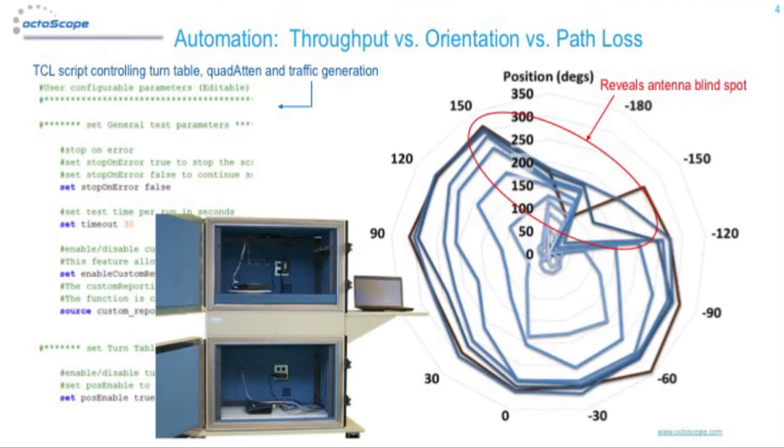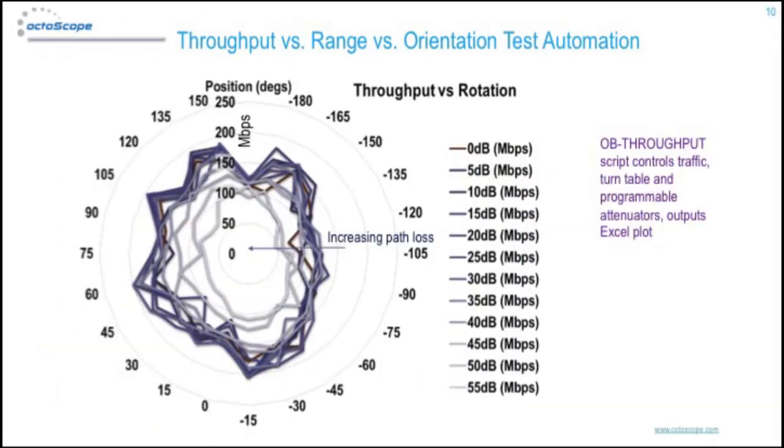Polar plots are also useful in understanding device performance. In this case, we rotate the device to distinct orientations, in this example every 30 degrees. At each of those points, we go through the number of attenuation steps programmed to get the plot shown here. It's thus easy to discover any issues with an antenna. In this particular example, the device we measured had a piece of metal blocking the antenna, and the results clearly show the resulting degradation in performance. Each point on a polar plot is an attenuation-rotation combination.